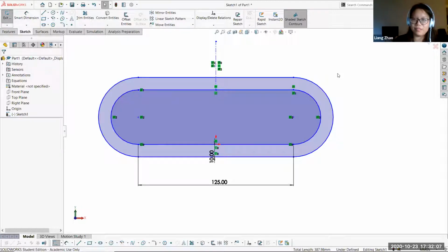Yeah. I was going to say, fun fact, this is very, very useful if you're dealing with trying to draft, for example, a box with hollow walls. Instead of having to take two profiles and then a cut, you can just use an offset to extrude a thin profile and be done with it.